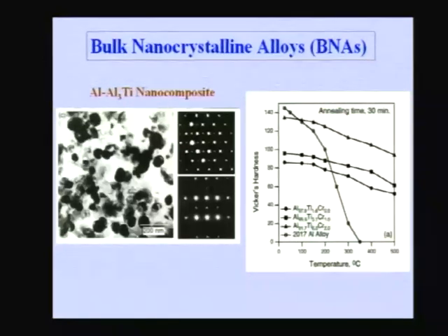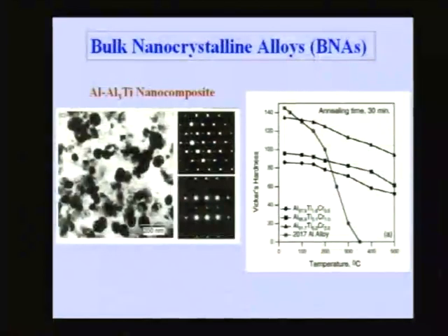For example, the top one gives you a 3-fold or 6-fold symmetry, which is characteristic of the 111 pattern, and you have fine spots at the center, and those fine spots are what are called the superlattice reflections. We know that in X-ray or electron diffraction, whenever you have an ordered structure, you get extra peaks or extra spots which correspond to the ordered nature of the compound.